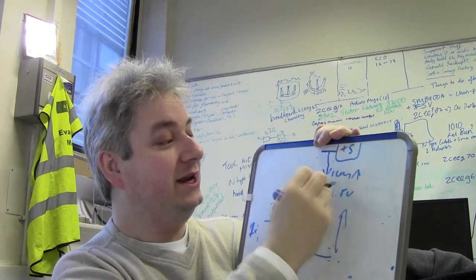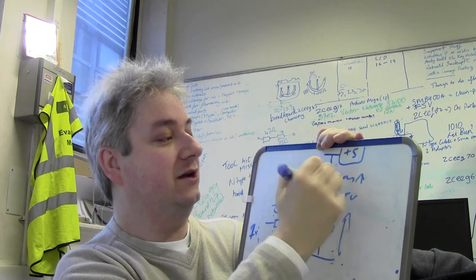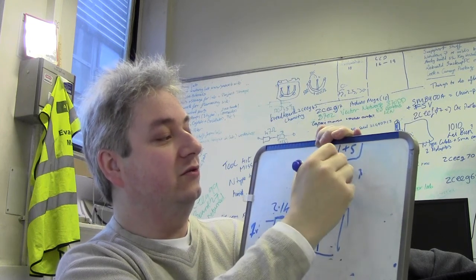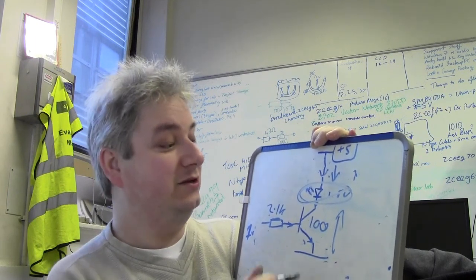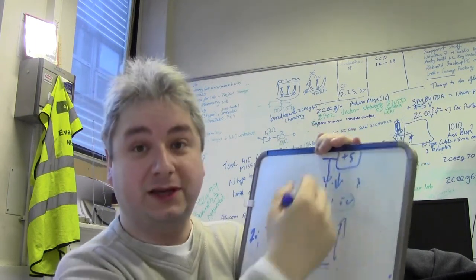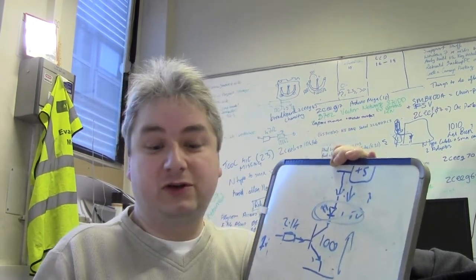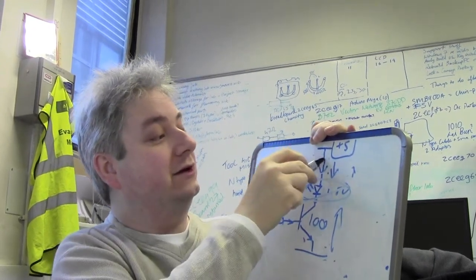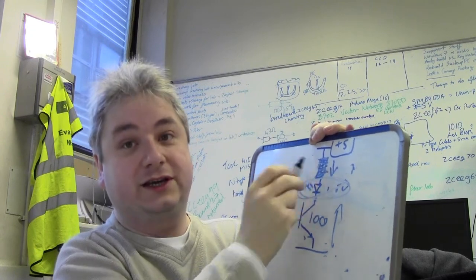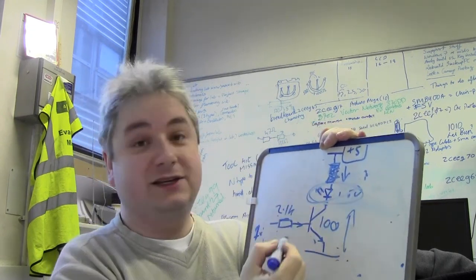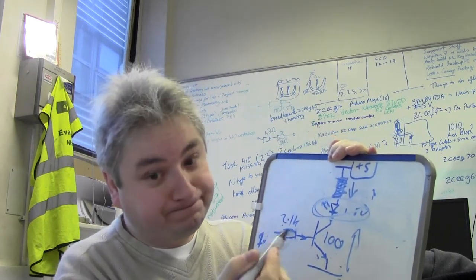If this goes up, you're going to have a higher gain, higher current flow. High current flow means that you're going to kill your LED. It's no longer your 10 milliamps because you've got maximum current flow through here. It's useless. So it's really good practice to have your little voltage dropper resistor up here. In this case, sometimes it's called a current limiting resistor because you're actually limiting the current.